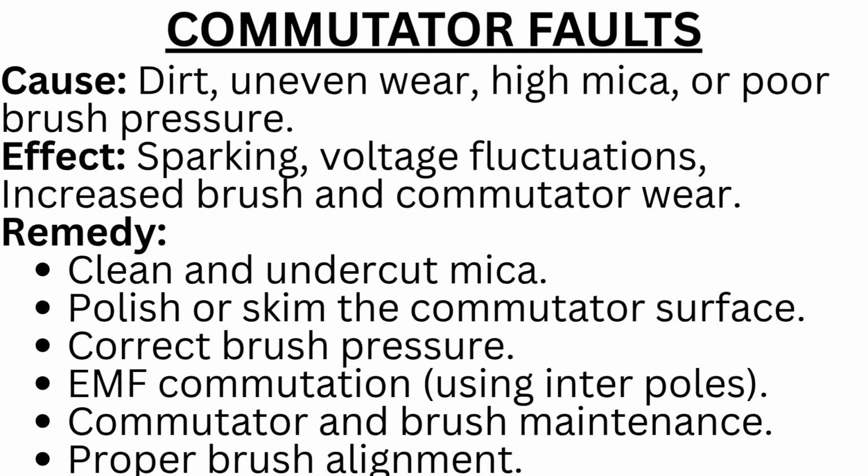The other electrical fault is the commutator faults. Cause: dirt, uneven wear, high mica, or poor brush pressure. Effect: sparking, voltage fluctuations, increased brush and commutator wear. Remedy: clean and undercut mica. Polish or skim the commutator surface. Correct brush pressure. EMF commutation, using interpoles. Commutator and brush maintenance. Proper brush alignment.